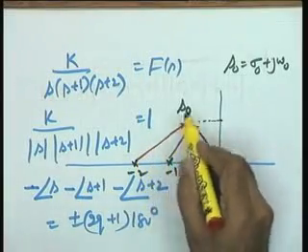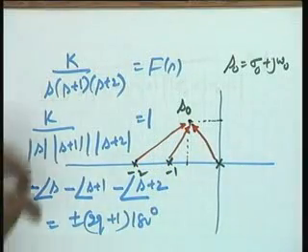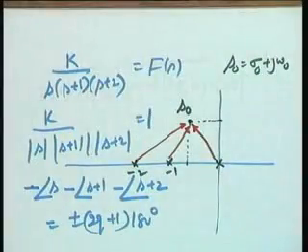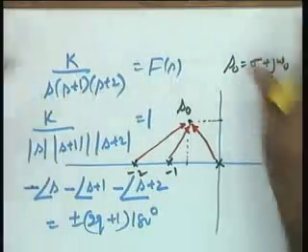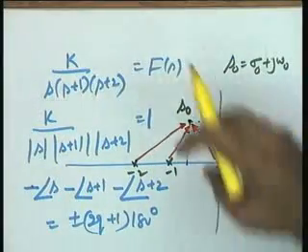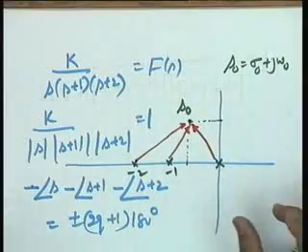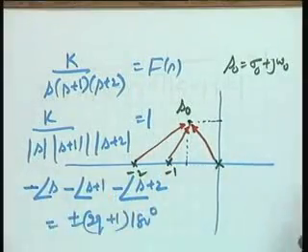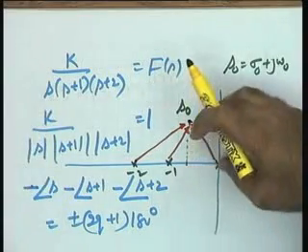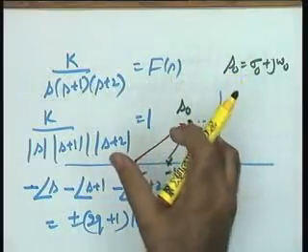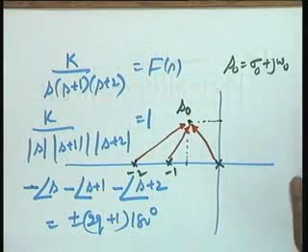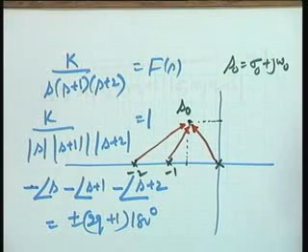So it means the magnitude condition will really not require testing or calculating these magnitudes all the time. If you have a graph paper, you can read these red distances to the scale by which you have taken these -1, -2. In that case, k divided by this distance times this distance times this distance should be equal to 1 for the magnitude condition to be satisfied.